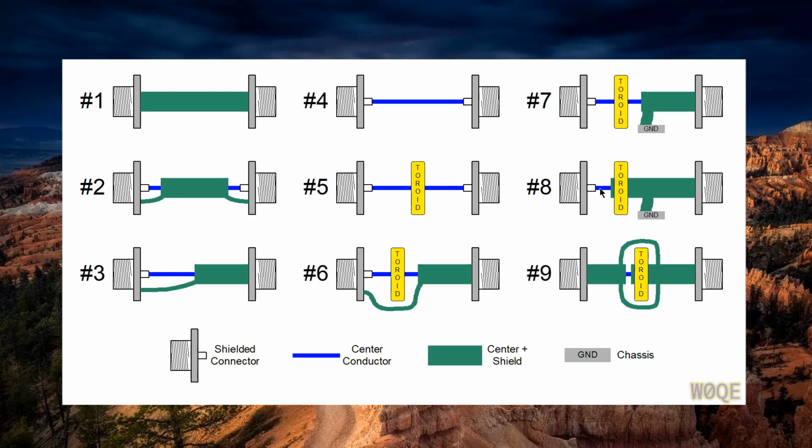This current on the inside and the outside cancel itself out, and all the toroid sees is the center conductor current. And again, this has a little bit of SWR because once you get here, you have to go back over, you have to get back to here. You could even do it better than that. You could maintain the transmission line through the toroid. You could maintain it on this side up to a small gap and then have a complete structure that surrounded the toroid. That would even be better. But the point I'm trying to make here is